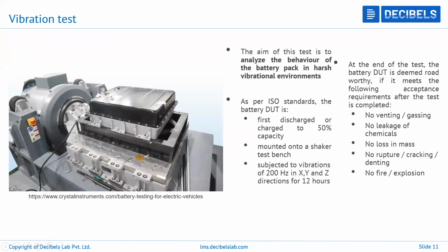Here, your battery pack is mounted on top of a test bench and subjected to a vibration of 200 hertz in all three X, Y, and Z directions for a minimum period of 12 hours. We know that in electric vehicles, there can be different sources of vibration from the motor, chassis, wheel, suspension, or from the vehicle structure itself.